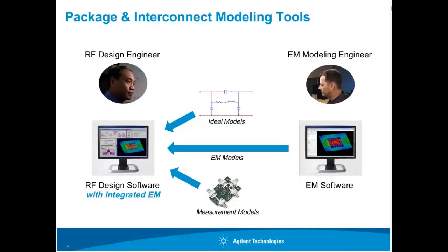Because of these inefficiencies, we've seen the emergence of EM simulation tools directly integrated into the RF design software. For example, in ADS, you can now run planar 3D EM simulations using Momentum, as well as full 3D EM simulations using finite element technology. This integrated EM certainly doesn't eliminate the need for standalone EM modeling tools, but there are some applications where integrated EM will be a lot easier, save lots of time, and really allow RF designers to move from a static design approach to a much more dynamic co-design approach. So the good news is that RF designers now have direct access to EM simulation technology in their design tools.